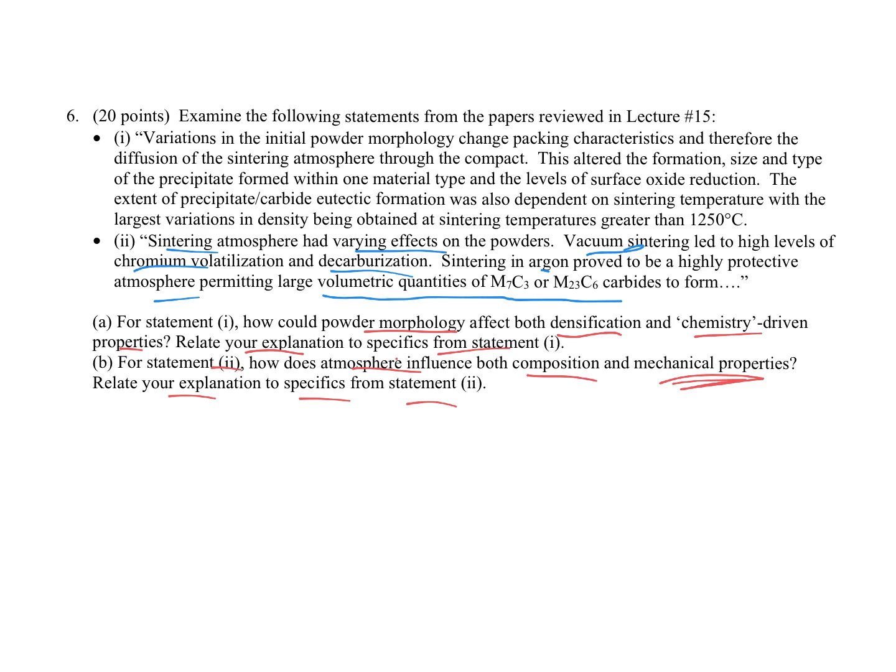Yeah, so it's not as straightforward as just atmosphere and a metal surface. When you make a three-dimensional object, you create gradients, and those gradients can influence properties as well as grain size, as well as composition. All right, but the main things here, we know that atmosphere is important. We know that throwing temperature and time at these microstructures is not always going to fix the problem. It can make the problem worse. We know that the atmosphere, which initially helps us, can end up hurting us depending on how we utilize that atmosphere.